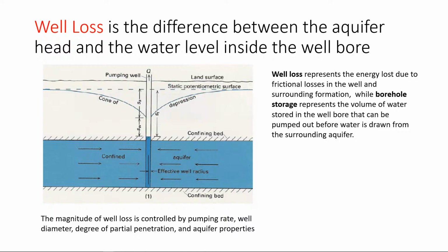Yeah, and of course, if you have a well that has a very large diameter or a screen for a very long interval, then this borehole storage could be considerable, and it could be a big amount that you need to consider.